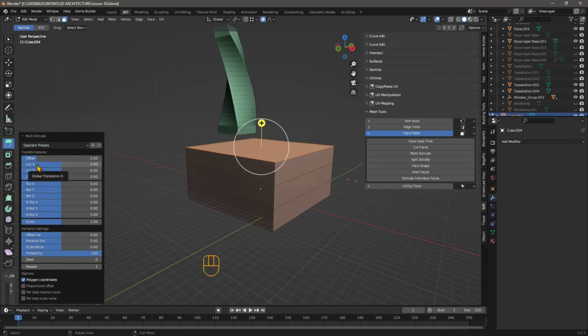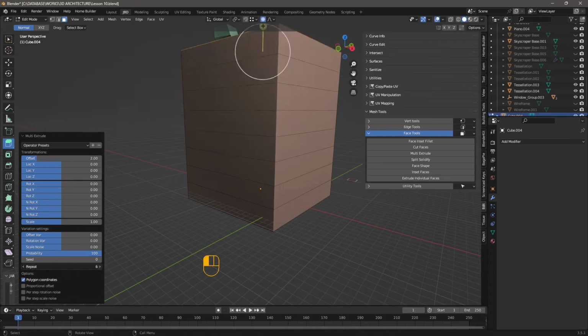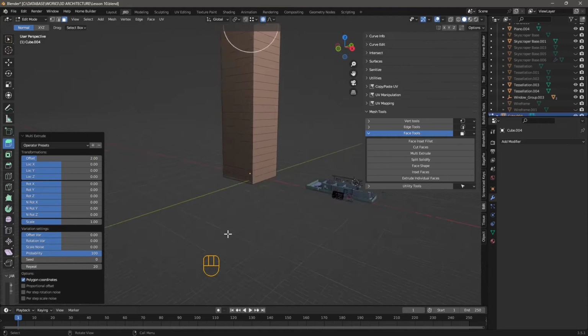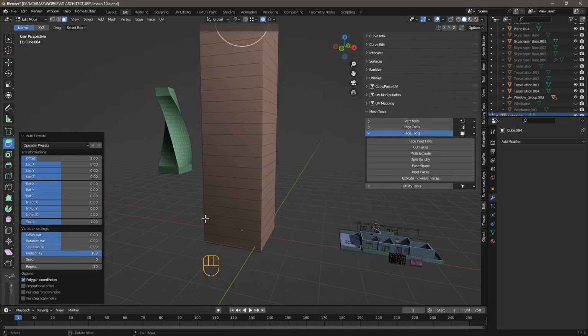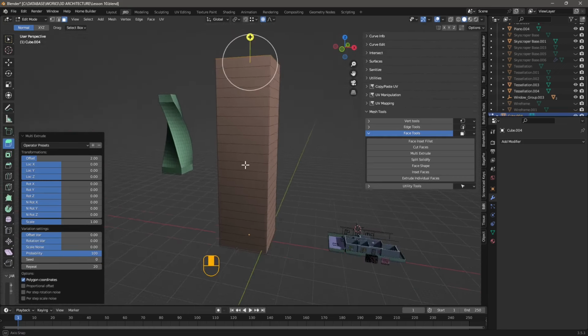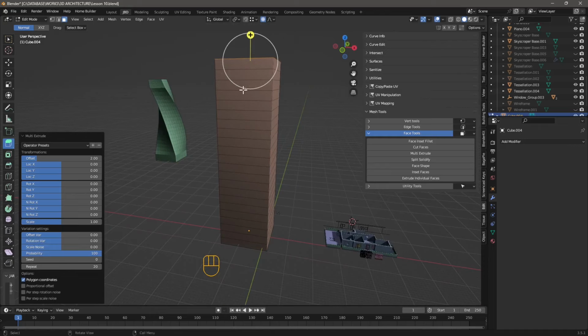And then we're going to increase the number of levels, floors using the repeat. So I'm going to click on repeat many times. I want to do this like 20 times, so it becomes a really tall building. And it's a little bit taller than that, but that's fine. We just need to concentrate on these parameters right here.